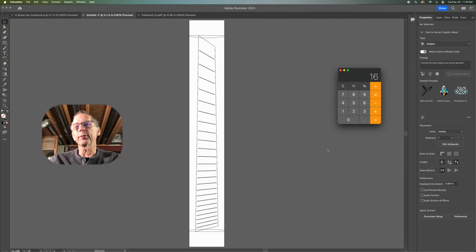And what I need to do is subtract the depth of the tang that will be pressed into that fret slot. Now I've measured the tang on the fret wire that I'm going to use, and it has a depth of 0.07 inches. So I'll subtract that from the 16-inch radius, and what I get is 15.93. So to draw a circle in Illustrator, I need to multiply that by 2 to get the diameter, which is 31.86 inches. That's for the heel.